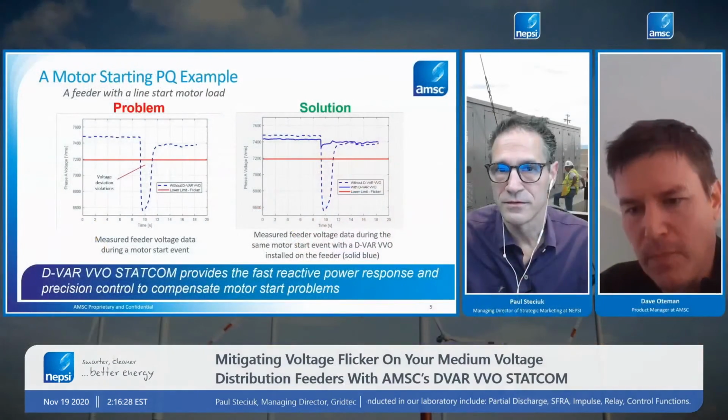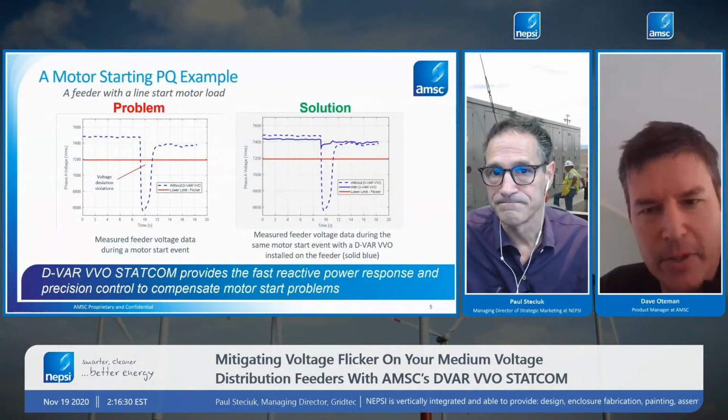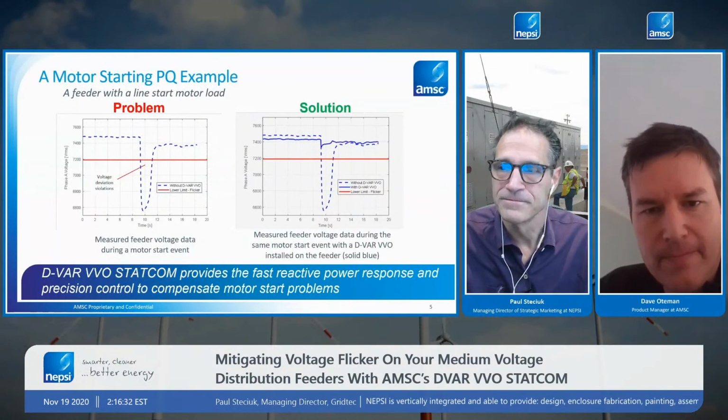Out maybe 8 or 10 or 15 miles, the pre-start voltage could technically be as low as 0.9, because electric utilities are only required to supply voltage between 0.9 and 1.1 per unit. So your designers have to account for a pre-start voltage as low as 0.9. That's a really good point.